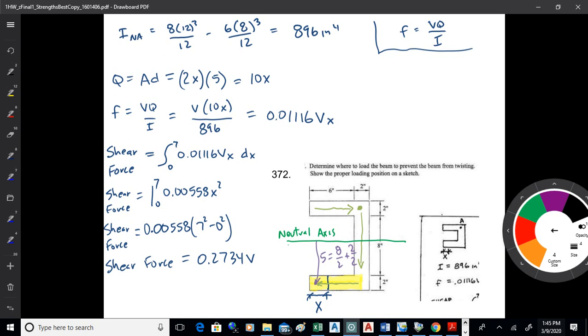Okay, so I sketch in what the shear is going to do. It actually does kind of flow through the object. Okay, you pick the centroids. Your reference points are kind of the centers of the different pieces of the C channel. So this point would be an inch in from both sides, edges. There's a point down there.